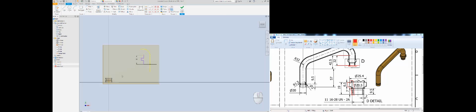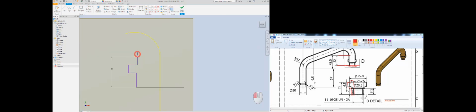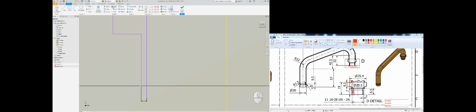I'm not free as on the other side. I have a limited size here. Also, I will go inside, and I will have a full thickness from this point to this point, 1.5 millimeters. I will make the trim for unnecessary parts and give the dimension. For this line, I will turn it to construction, create a new line, and make this line a center line to give the dimension constraint.